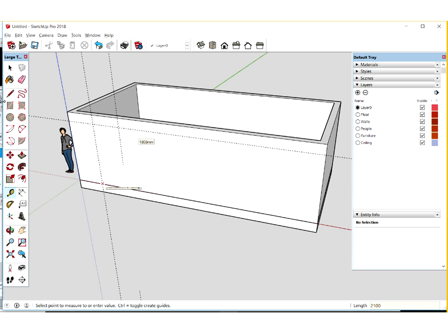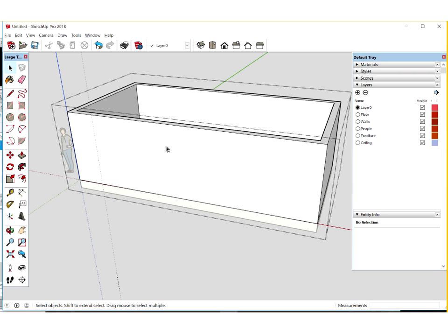So remembering that if we're going to cut this door into the walls, the group, so we need to double click on our group first. You'll see that now it's activated. The other things are slightly faded in the background. I can just use the rectangle tool here on that intersection between the guideline and the wall. I'm going to click and start drawing, and then look down the bottom right of my screen. I can see there which is going to need to be the width and the height, because I'm already making the box roughly that size. So I'm going to do 920, comma, 2100 for the door.